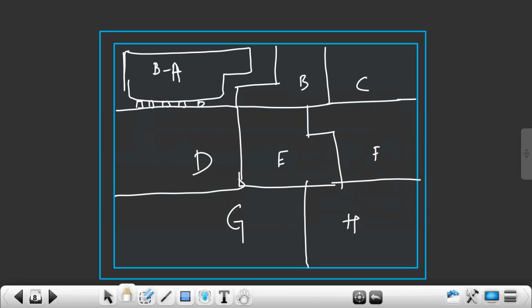If all the outputs of block A are going to block B, then all the output ports you have to place here. So all the output ports of block A you place here, and all the input ports of block A you place here. This has to be decided from the full chip design only.